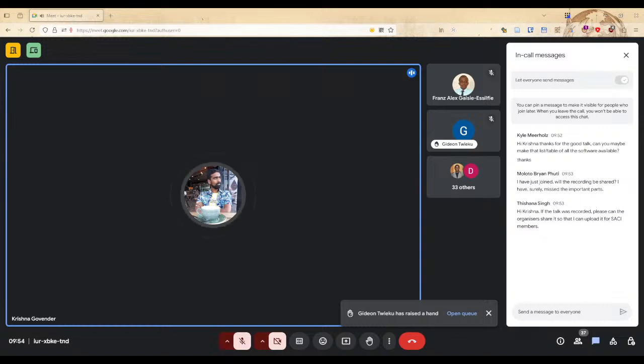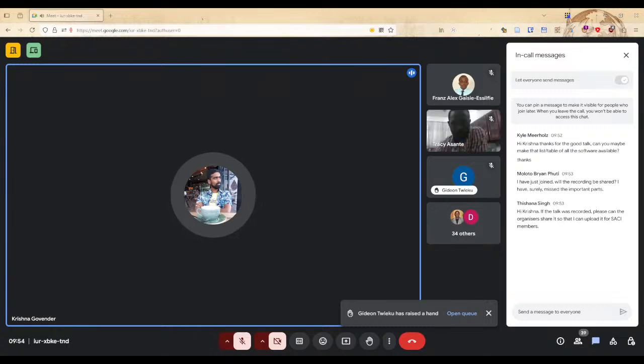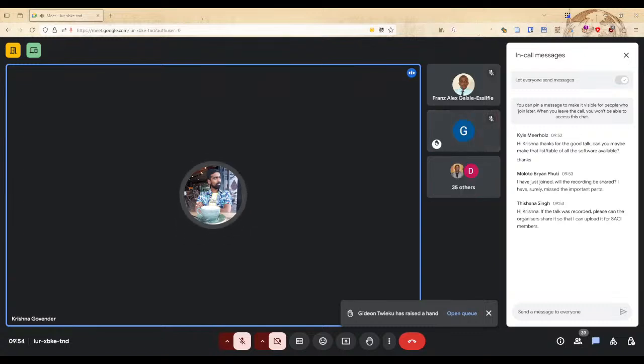So instead of saying 100 nanoseconds, if you work it out, you drop it down to 20. And then you use exactly the same input for the next iteration. The only thing you do with Gromacs is tell it to restart from the previous one. That way it'll start from, say, 21 upwards to get to wherever it needs to be. And then for the piecing part, there are scripts available, whether using Gromacs, Amber, doesn't matter.